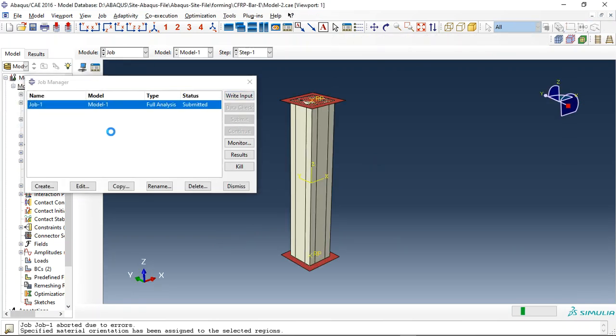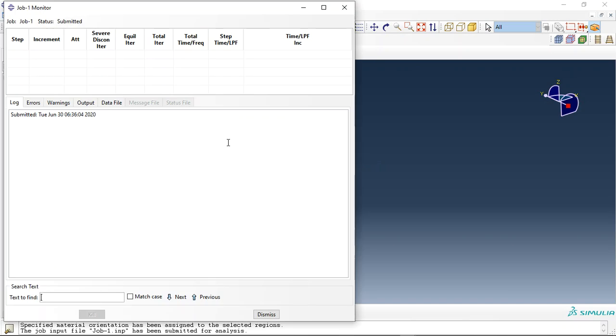Okay, monitor. This is the anisotropic material. We need to assign direction to it. It is a circle, and the normal in each node should be on the outer surface of the cylinder, and we created that just a minute ago, the normal direction.